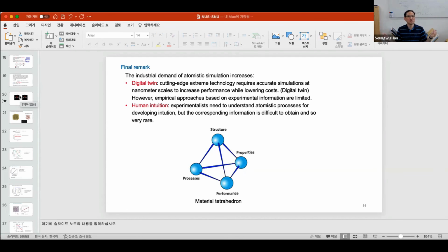Experimentally it is hugely fast, but at simulation scale it is a very, very slow process, and therefore we have to shorten the melt-quench time such that it is at least 100 times faster than the fastest cooling speed that we can achieve in experiment. That's one artifact, but it is inevitable.